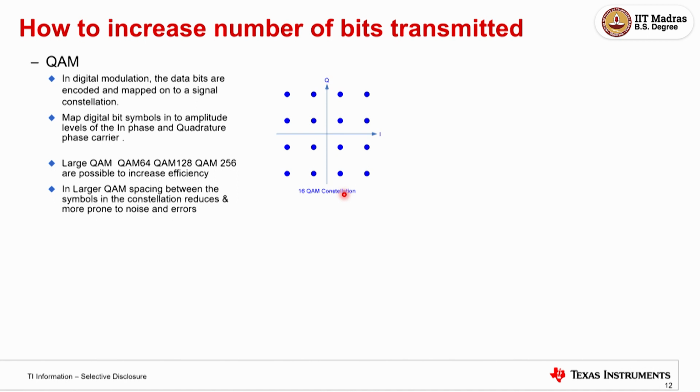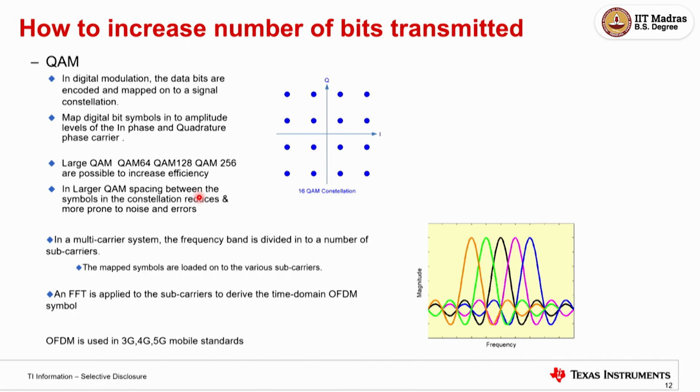That's what it means. But okay, we'll go back to that. We'll see what this is in a later perspective. But the one thing you can clearly figure out is that as you keep increasing this QAM, they are going to be more dense. You will have more points, and the points are going to be very close. Within the same area, I have to put more. 16 by 16 means there will be a lot of points here. The spacing between the points will be very close. That's natural. Your grid will just be much denser.